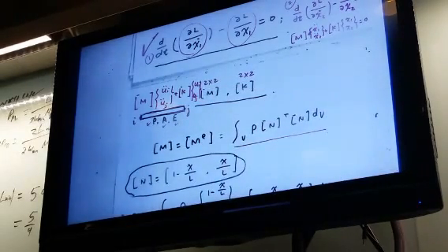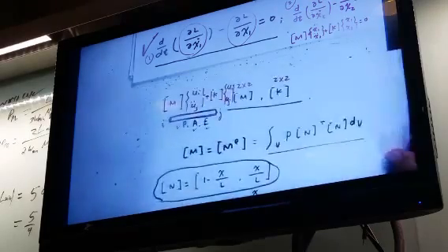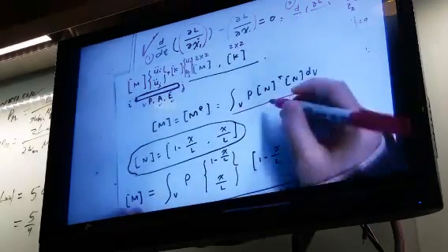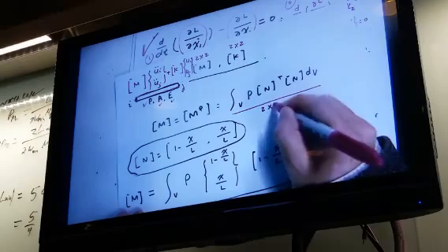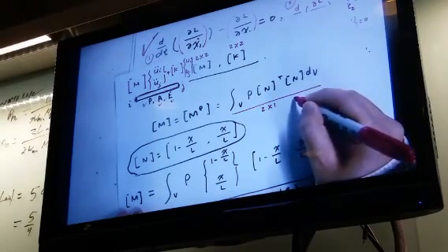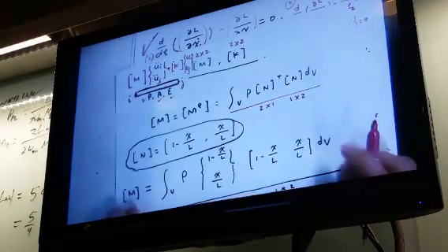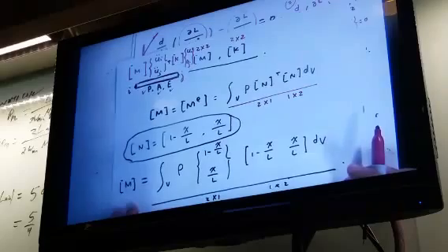Parallel to the spring mass system, there are two unknowns x1 and x2. Right now, you just change that spring to a bar. So you will have ui and uj, which are two unknowns. And that means the dimension of M and K has to be 2 by 2 for this bar element. If this is the definition, that means this N is 2 by 1, and this N transpose is 1 by 2.